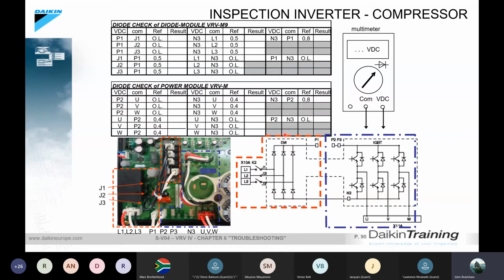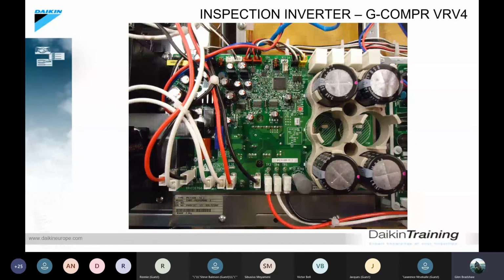And you can see that these items, I'll show you now, another way of going before you do the test is to identify the areas that you need to have. And you'll see that they are all diode checks, but they have varying values, and you're allowed a 10% discrepancy in those over there. So basically, that's what the PC board looks like from the top.